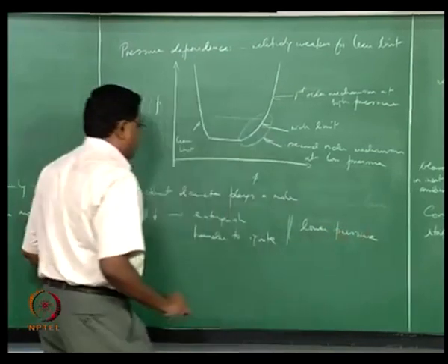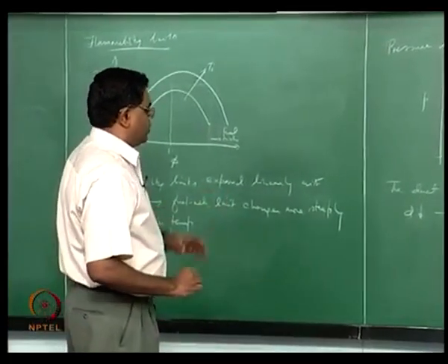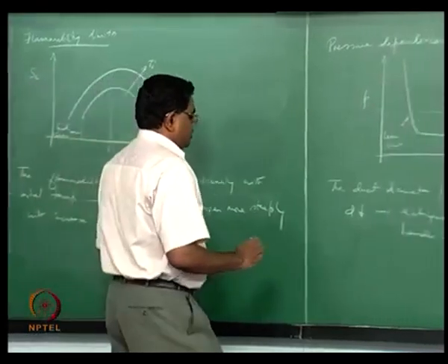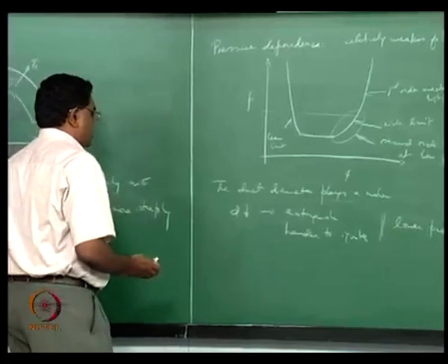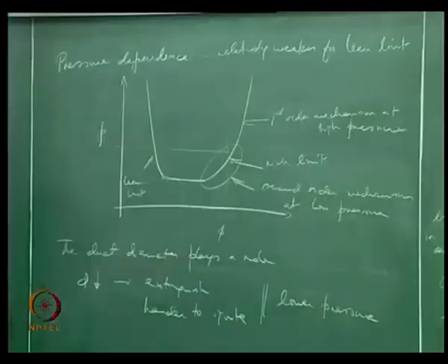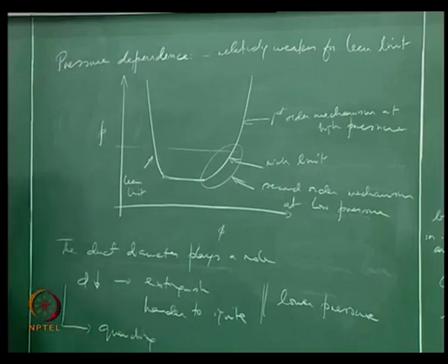So you now have a fairly good sensitivity of the flammability limits to the duct diameter at lower pressure, essentially because of the difficulty to ignite, or even if you ignite you could have an extinction happen within a narrow range of equivalence ratios, giving a fairly narrow range of flammability limits correspondingly. And I'd like to point out that this leads to something called quenching, which we will discuss next.